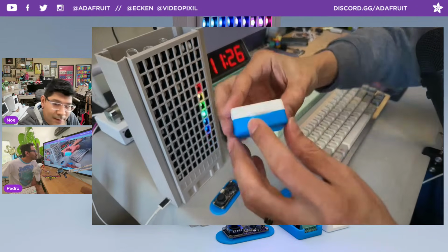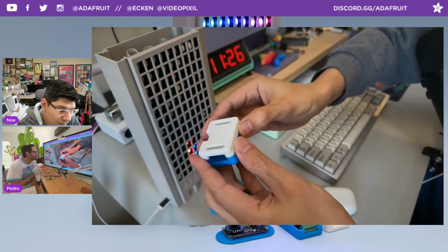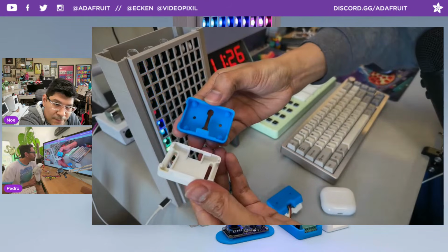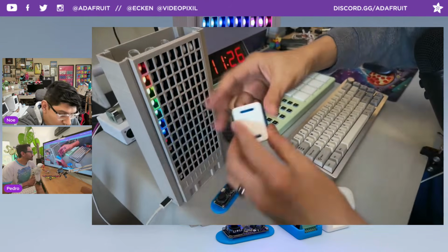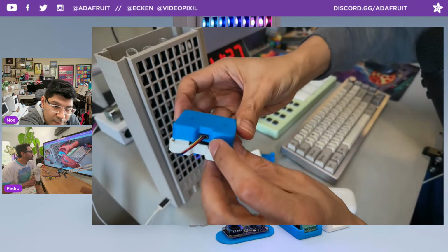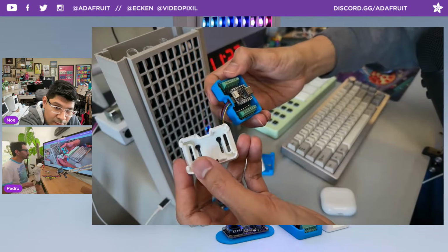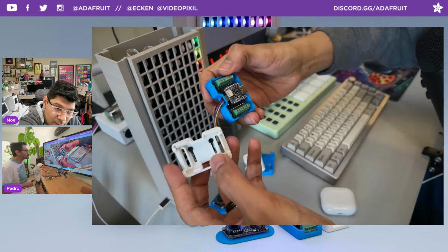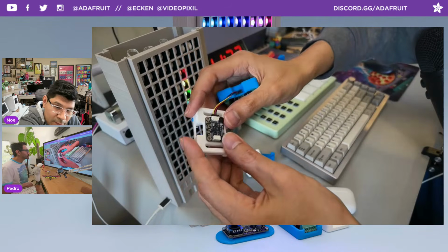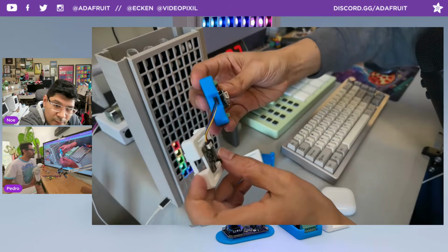Here you can see one of the other iterations. Same thing. It allows you to just get your fingers in there so that you can open it like that. Nice. This is like V1, and this is like V2, where it has that open access port for the Stemma QT. Then you can see how it's mounted here. You've got these two rails. It's a slotted rail, M2.5 sized for the M2.5 holes, so you can reposition the Stemma QT board how you want. So that's how that's working.